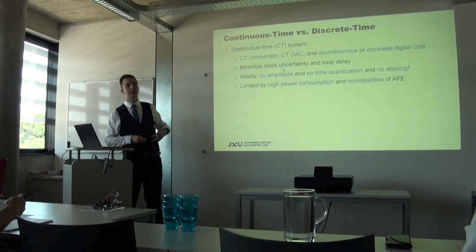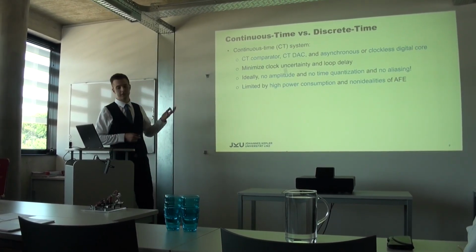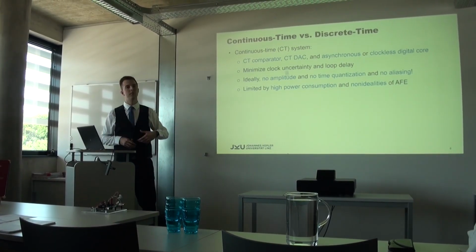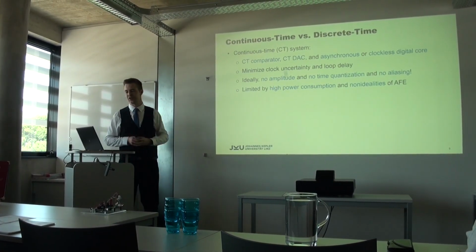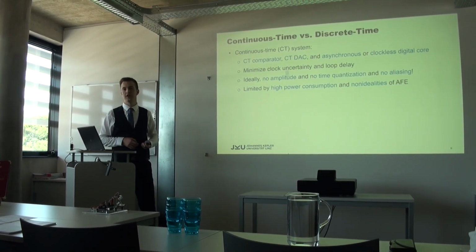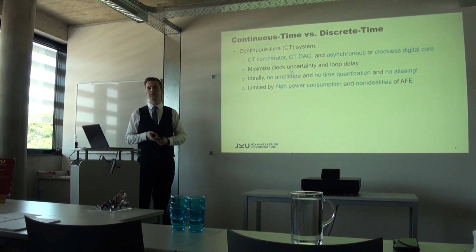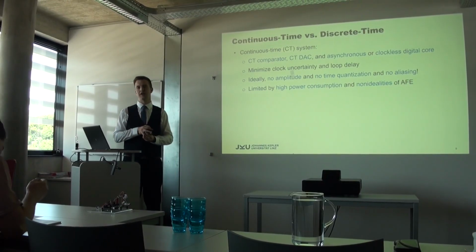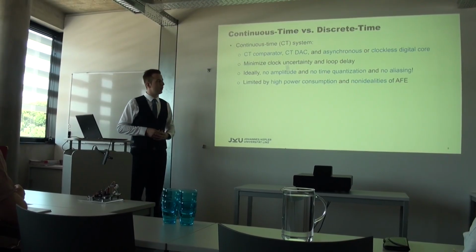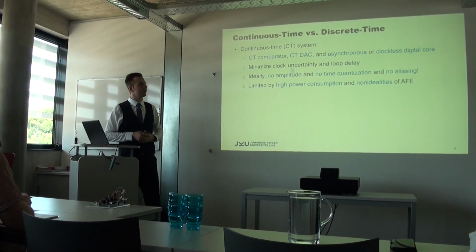And then we can build the analog front end in two ways. The first way is continuous time. So we have a continuous time comparator, a continuous time DAC, and an asynchronous or clockless digital core. So we can here minimize the clock uncertainty and also the loop delay. Ideally, these ADCs have no amplitude quantization, no time quantization, and no aliasing, which is really incredible. But they're limited by the high power consumption, because they always consume power, and of course the non-idealities of the